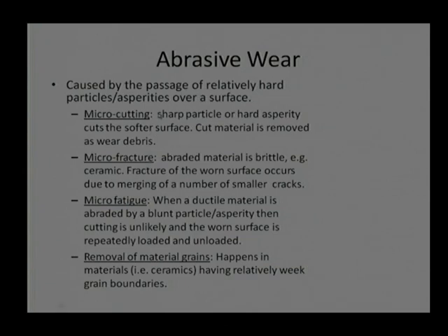And whenever particles or material are removed from the surface, we call this wear debris. If the material is getting displaced, maybe initially due to fatigue or some sort of flowing effect, we will not be able to gain any wear debris, it will be just a surfacing of the surface. Wear debris is a loose particle, and those loose particles may further increase or decrease the wear rate, depending on the operating parameters.